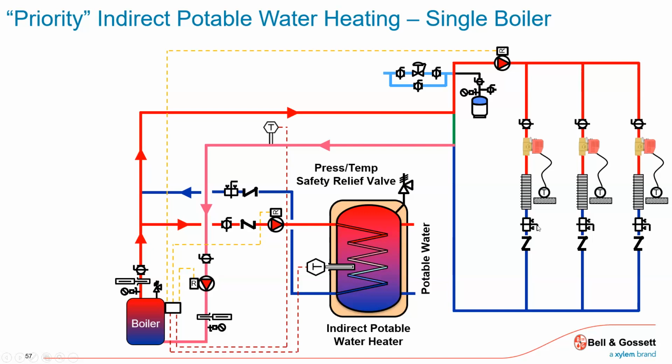Now, all of a sudden, I'm taking hot boiler water through the coil, heating up the water, taking a delta T, a temperature drop, putting it back on that loop. So there's my priority. I'm grabbing all the energy that the boiler has right off the bat. Whatever temperature drop I have left, that's when I'm feeding my zones, perhaps. But I prioritize it just by the location and using closely spaced tees.